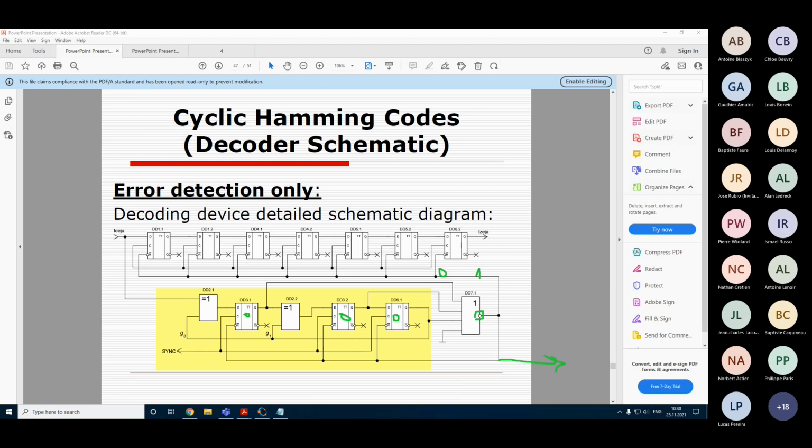So basically the logic now is inverse. If 1, it's okay. If 0, it's an error. So 1 does not reset these flip-flops because they are reset by 0, and 0 can happen only if any of these elements is 1, for example this way, or this way, or even this way. All of them will produce symbol 0 at the output of this NOR gate, which will then reset all flip-flops, erase the received data, and request retransmission.